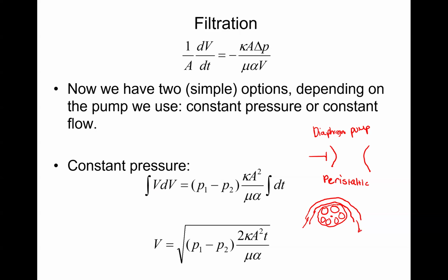Versus a pump that works based on pressure. At a constant pressure, for example, and similar to how we did the problems in packed beds, you have centrifugal pumps where you have basically one of these centrifuge systems. The fluid enters through the center and leaves on the side. You probably have seen some of these pumps, they are very common, and these typically work at a pressure relationship rather than a flow. And when systems like these where filtration occurs are very low flow, then the correlation is that this pressure is more or less constant. So you can assume a constant pressure.